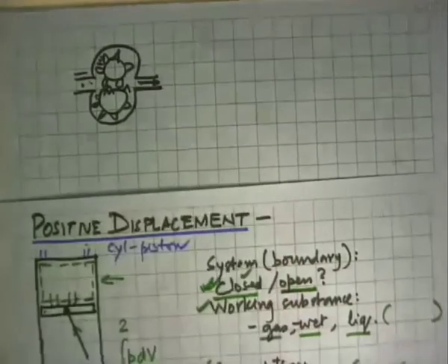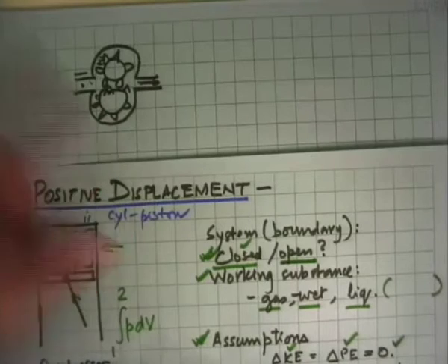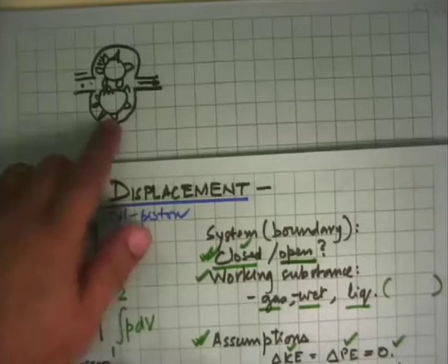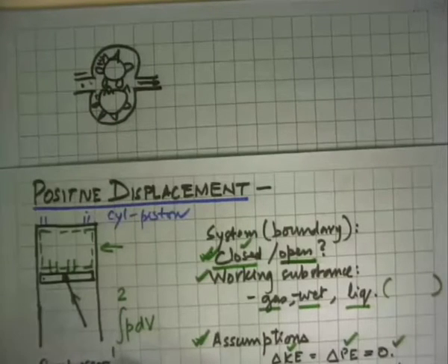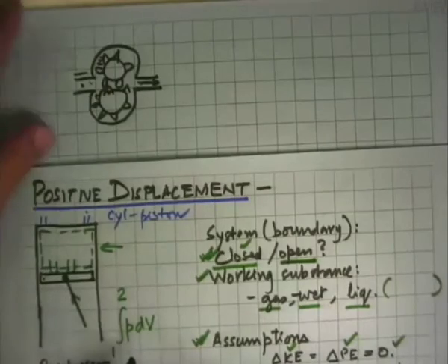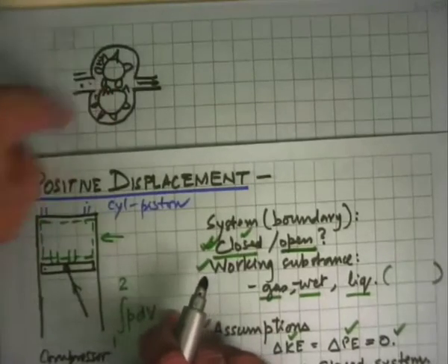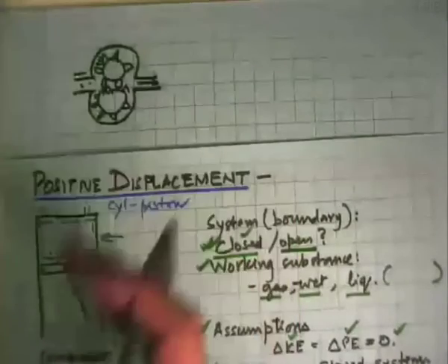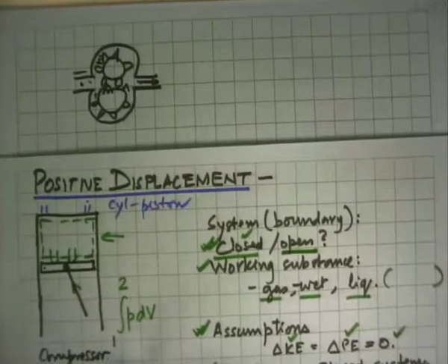You won't see any diesel engine or petrol engine anywhere which doesn't have at least one of these for lubricating oil, and possibly a second one, definitely for diesel engines, for feeding diesel fuel up to the engine. So a typical engine will have two gear pumps, two positive displacement devices. Screw compressors, as I mentioned, are two screws in mesh, so the flow happens normal to the plane of the paper. It is very difficult for me to show it here, but we can see some pictures of screws later on and see how two screws in mesh can be made to behave like a compressor.